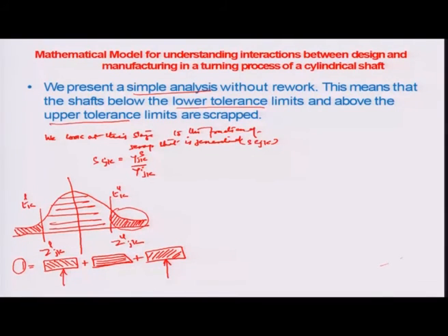to be taken off from the cumulative distribution function which we had provided in the last slide, in which we talked about 1 by root of 2 pi, integral minus infinity to z, e to the power of minus t square by 2 dt. This value of the integral, or area under the curve, is for z, which is the distribution x minus mu by sigma, so a scaled distribution. Obviously, we can find the values of this numerical integral and record them, and these are also available as standard tables from which we can find the percentage which is being rejected on either side of the upper and lower specification